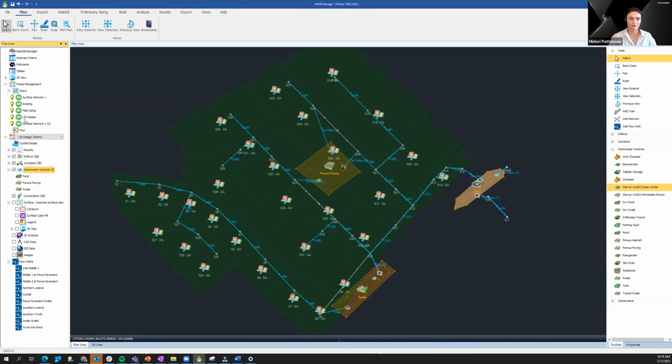When you run the model, you have the opportunity to run all of these different phases at once, or you can toggle them on and off. And it's also super easy to duplicate these phases so that you can start to add additional stormwater control structures. You can start to play with some of the inputs, again, change those pipe sizes, change the different outlet controls, and optimize your design.